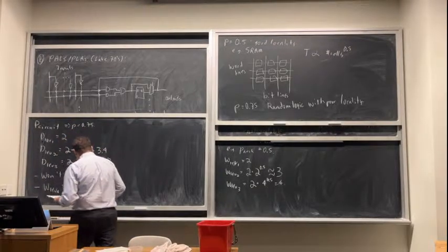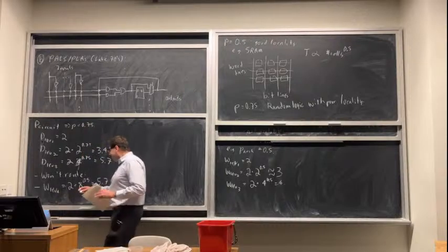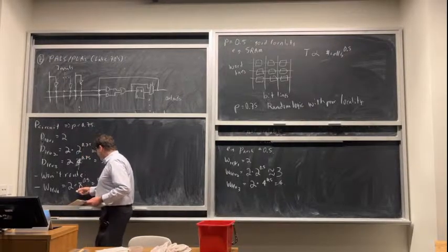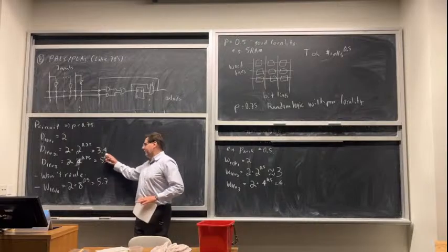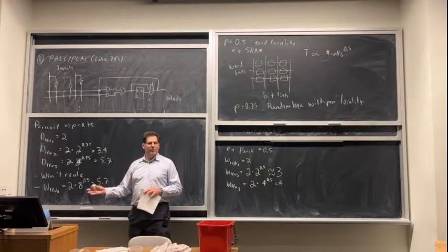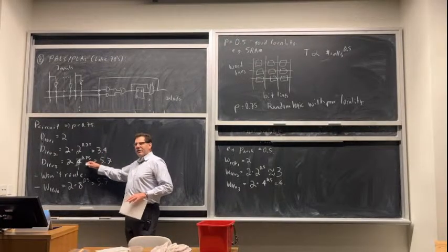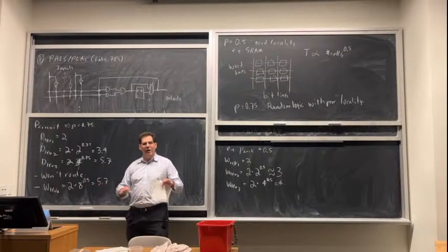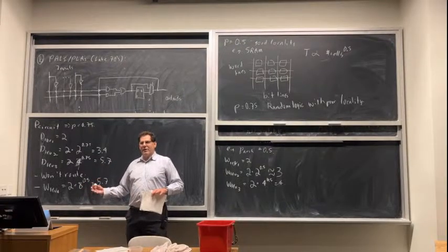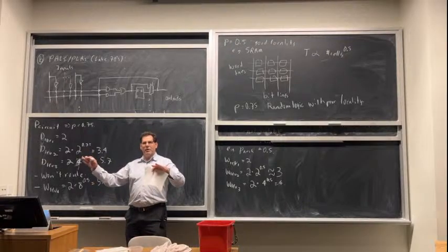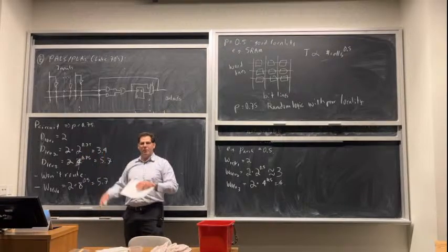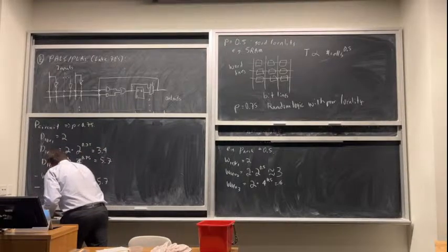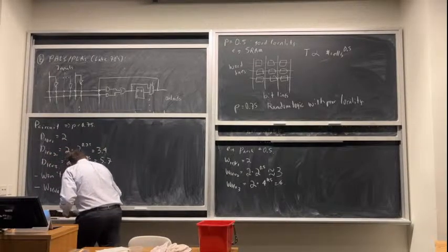So basically the level of hierarchy that has 8 logic units has enough wiring to support this circuit's demand when it's only using 4 logic units. It means I could put this circuit in this bigger chip, but I can actually only use half the chip. I've got to leave half the logic blocks unused, so I'm basically skipping over some of the routing hierarchy levels and just getting up to the fatter ones higher up. But this is only 50% utilization.